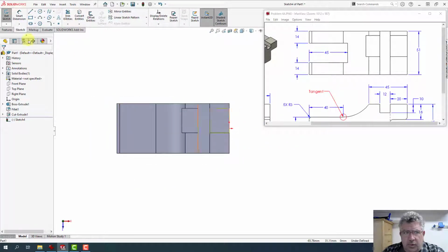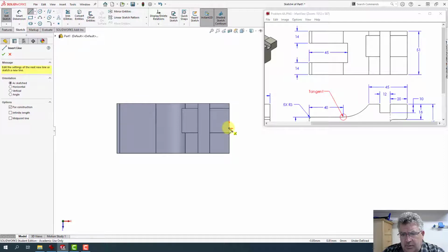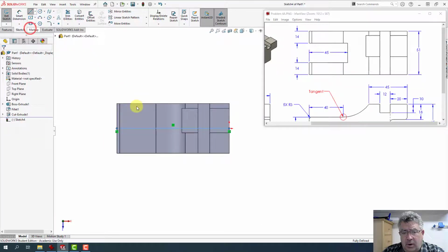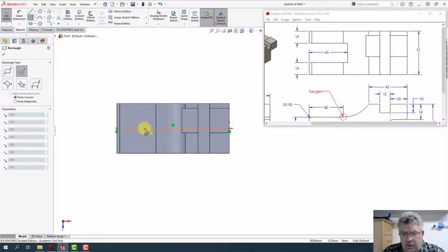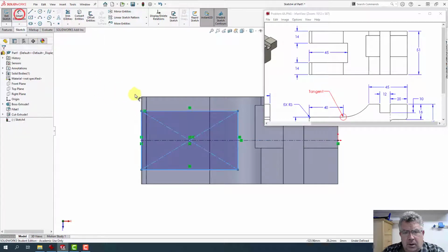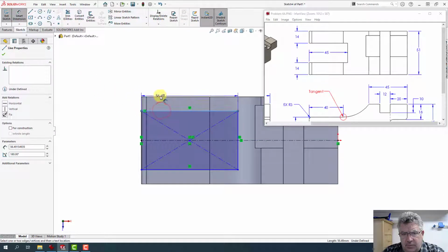Here's my center point. So I can easily utilize that to create a center line that I can then utilize my center rectangle. So I'll just select somewhere on the line, come over and make sure I grab the edge over here so I have a coincident to this edge. And I just put 2 dimensions in this case.